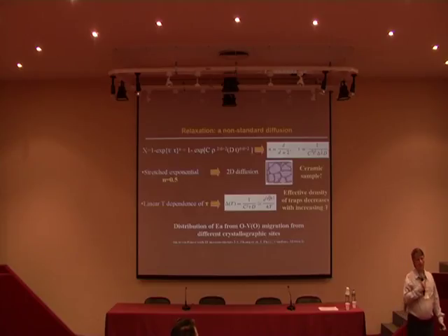Well, in YBCO, it's not the most usual way of diffusion, but I think this is probably because we have diffusion in grain boundaries. We know also that when we apply the pulses, when I showed you the superconducting transition, we change the width of the transition. So probably all the oxygen we are moving is located at the grain boundary. So I think this is a diffusion there. So okay, we can have voids or something like that. Voids, yeah. Okay.